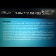Suspended solids that go through screens and grit chambers are removed from the sewage in the sedimentation tanks. These tanks, also called primary clarifiers, provide around 2 hours of detention time for gravity settling to occur. As the sewage flows through them slowly, the solids gradually sink to the bottom. The settled solids, known as raw or primary sludge, are moved along the tank bottom by mechanical scrapers. Sludge is collected in a container where it is drawn out for removal. Mechanical surface skimming devices remove oil and other floating materials.